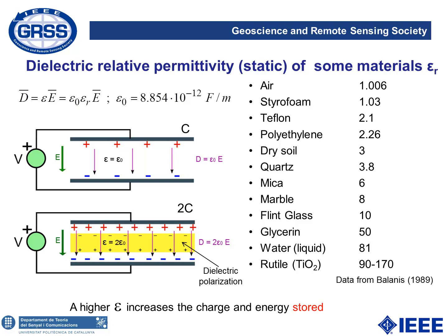So what do these permittivities mean exactly? Well, permittivity is the capacity of the material, or the electrical charges in the material, to become aligned with respect to an external electric field. This corresponds to a capacitor. This is just an example to understand what's going on with the dielectric polarization. We introduce a dielectric inside the capacitor plates, which produce a more or less constant electric field.